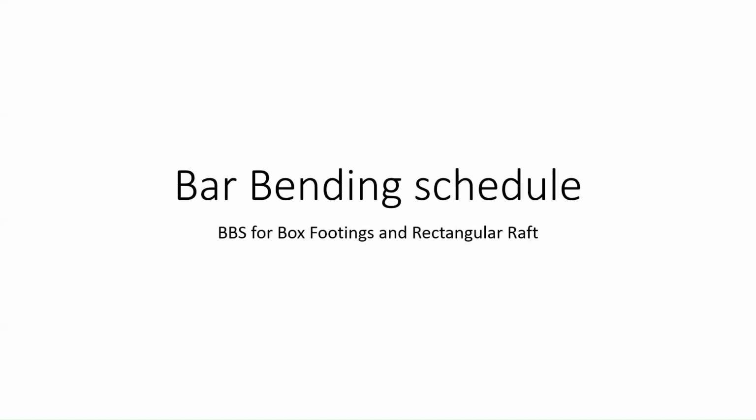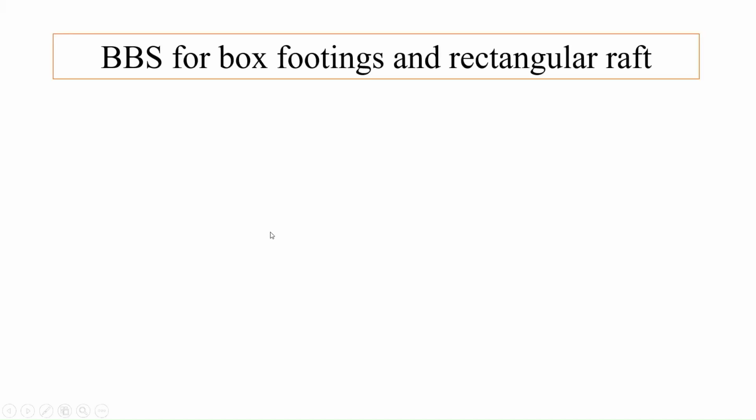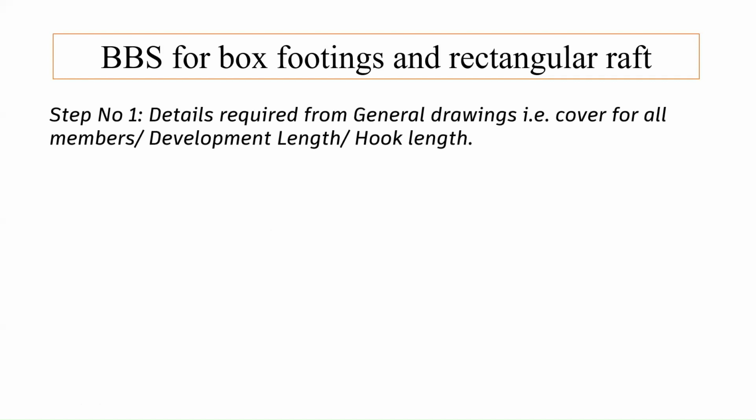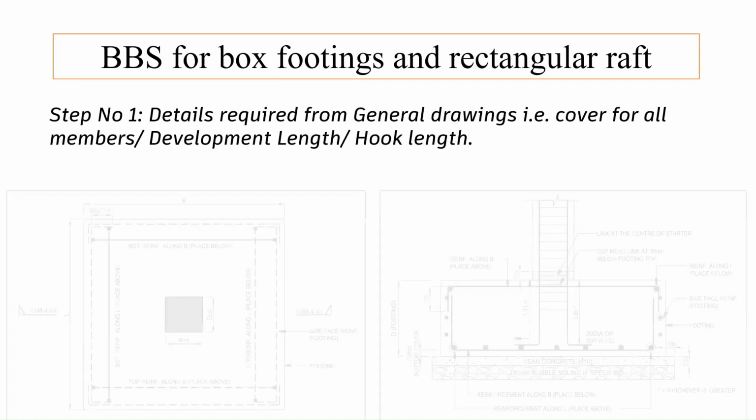In today's session, we are going to see how to calculate bar bending schedule for box footings and rectangular raft. To begin with, step number 1, we have to note down some details from our general drawing, that is cover for all members, development length and hook length.